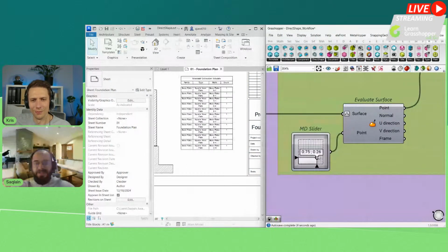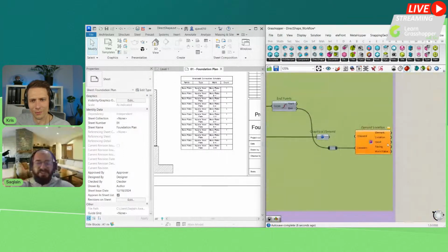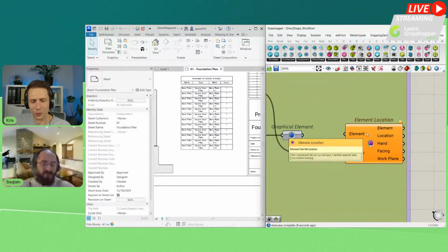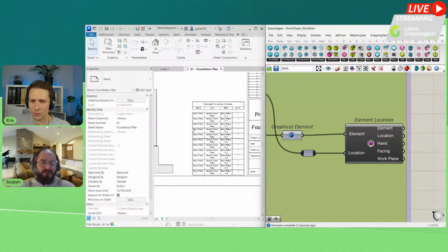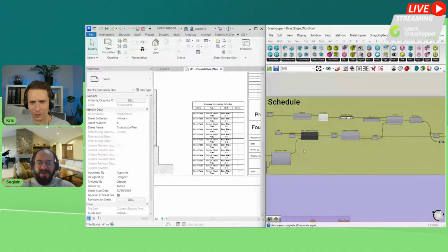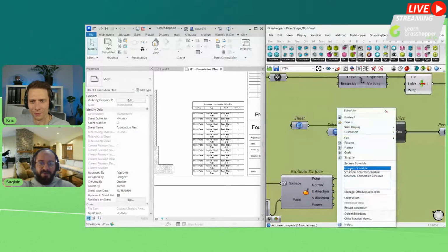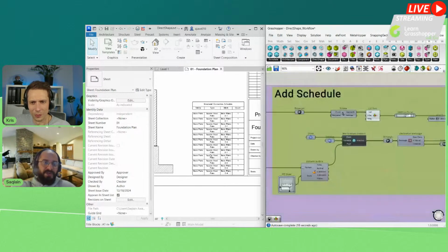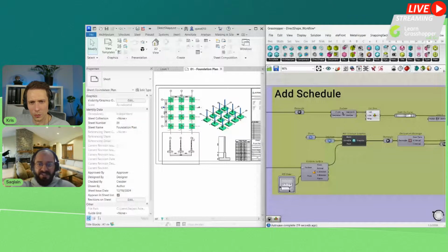There is one component which basically allows you to set the locations of your elements after you place them in Revit. So in this one, I have created this logic here. Whenever I place a new schedule here, it should be aligned with this line. And it doesn't matter if I change the schedule here, it will automatically be changing the schedules and placing them automatically. Similar thing you can do here with your sections also.